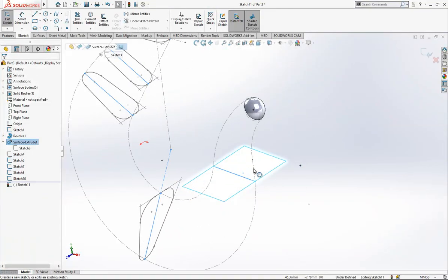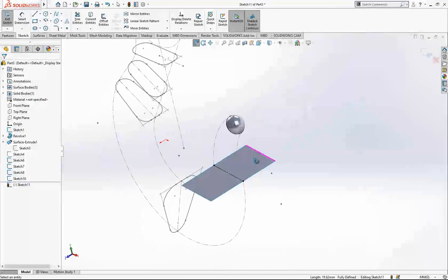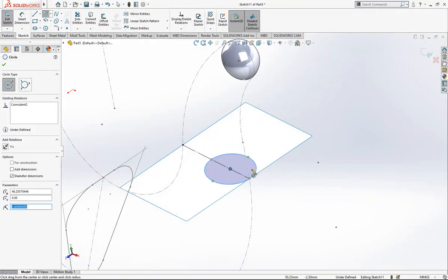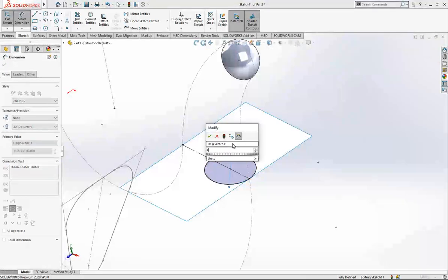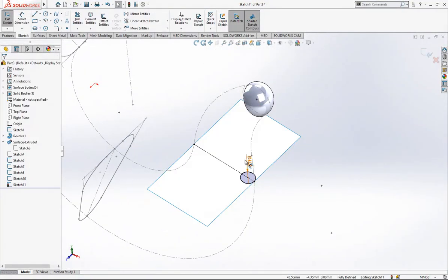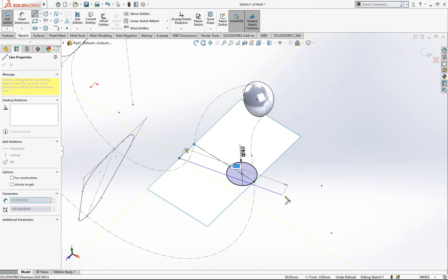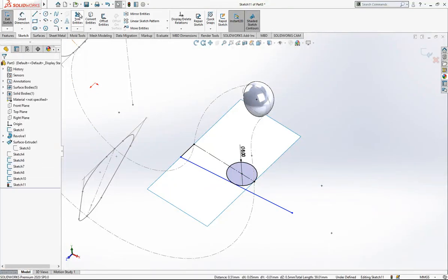We look here and we say convert this for me, as a construction geometry. Here I place a radius 4 now, radius 4, diameter 8, and from here to here I make a tangency.